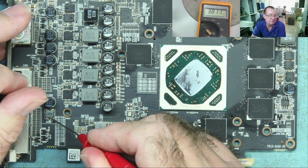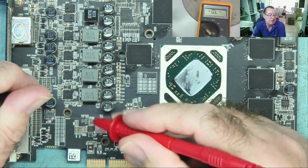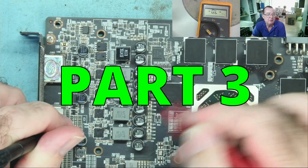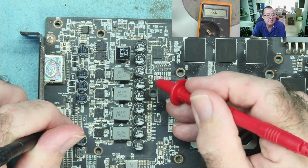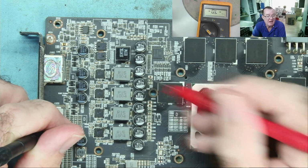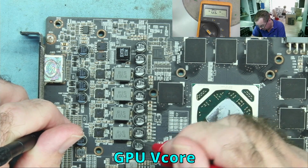Yeah, 2.7k, something like that. We know we have 3.3 coming in. We know the 5 volts on the back, so that's probably the 1.8, but we'll measure them in part 2. At the moment, we're just looking at resistances. Now, this one is different to these 4, okay? These 4 are probably all connected together and they're driving the GPU, and you expect this to be a very low resistance.